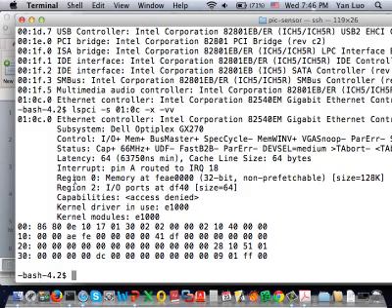It also shows that I have two regions. Region 0, the memory, is starting at this address, and region 2 is an I/O resource, and the address starts at DF40. Still a mystery: how does the system know about this? How does this Linux box know about this address here and that model number? These 4 lines below show you the actual 64 bytes in that PCI configuration space.